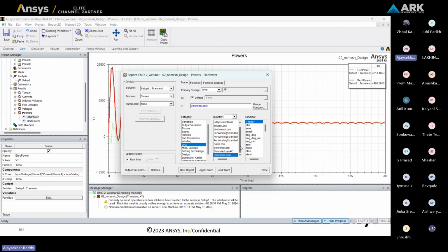Right now we are interested in total copper loss, right? So obviously the rotor will also have the copper loss, sorry, not copper loss, variable loss. So I square R loss, you can say. The aluminum bar conductors are solid, right? So this will come under the solid loss category. So I'll just copy this solid loss and standard loss R, add it and paste.